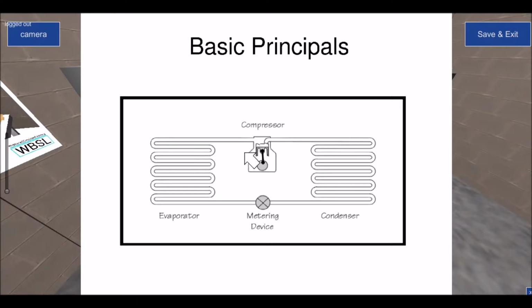Refrigeration compressors in the main are designed to pump vapor only. They don't pump liquid, and therefore the reason why we would have superheat in an evaporator, especially on commercial refrigeration plants, is for the very reason to protect the actual compressor from liquid getting back.